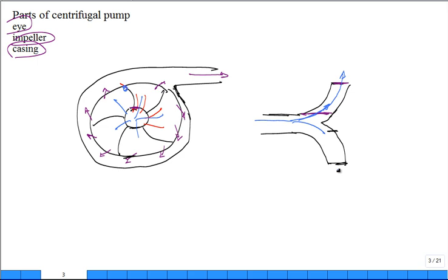Some pumps are really cheaply made. Some of them, they spend a lot of machining time and engineering analysis time on, such that they're efficient. The mechanical efficiency is higher. This is all connected up with a shaft, and this whole shaft is rotating like that. So this is showing you the fluid passageway: the fluid comes in and goes out off of those impellers. It's collected in a region here, and then up here it's an even larger region because it needs to discharge into the pipe.